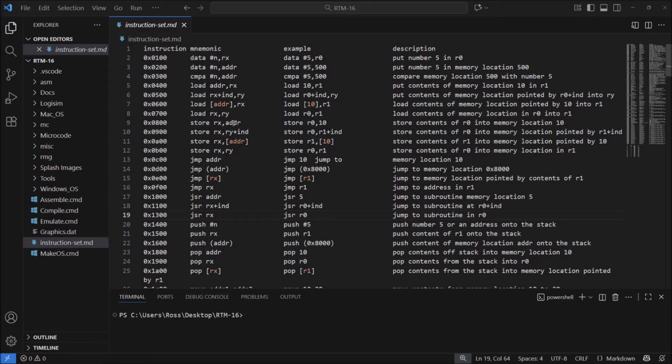So it means that the microcode or the micro instructions for this store instruction and this load instruction are exactly the microcode that we require. So we could in effect just copy the microcode from these and put it into the microcode for our new move instructions. So what we're going to do next is show you exactly where we're going to get this microcode and how we're going to change everything so we can make it all work.